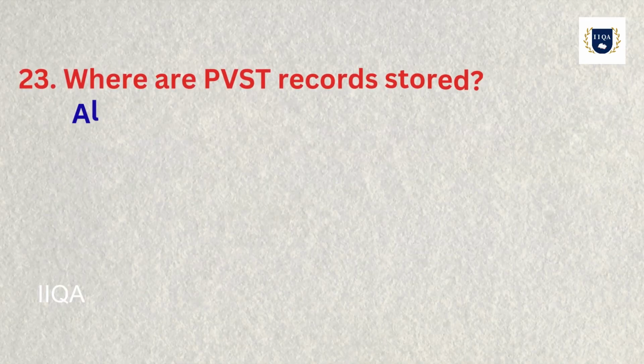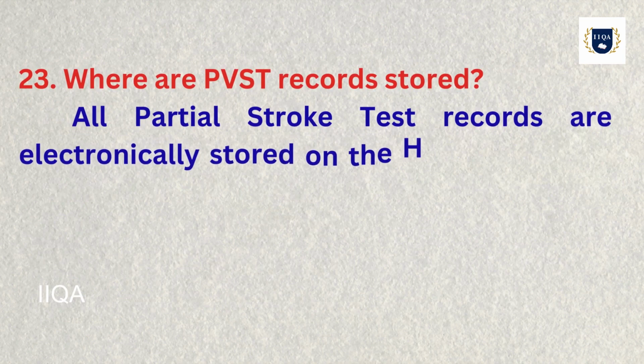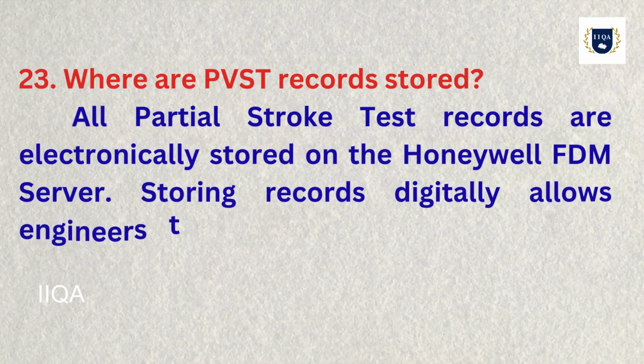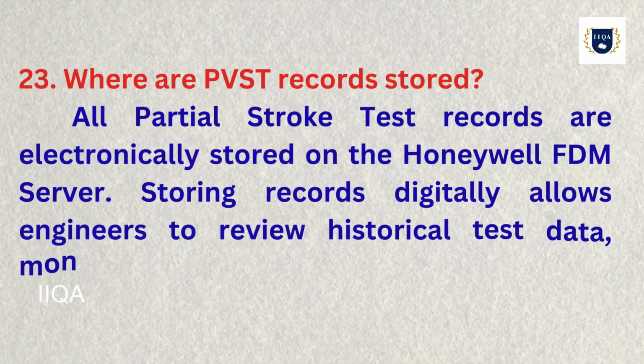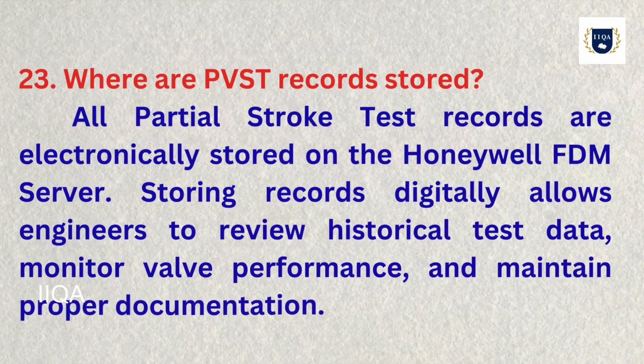23. Where are PVST records stored? All partial stroke test records are electronically stored on the Honeywell FDM server. Storing records digitally allows engineers to review historical test data, monitor valve performance, and maintain proper documentation.